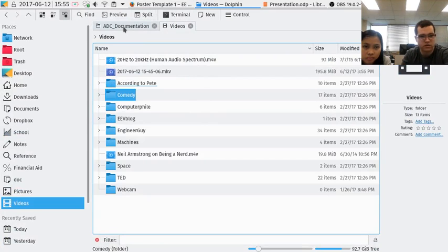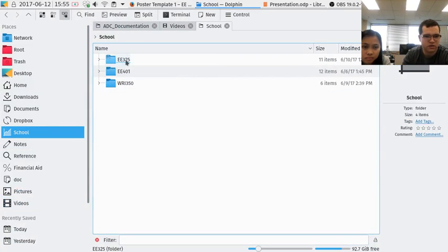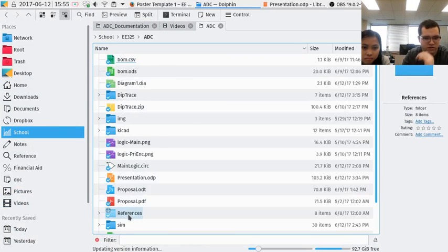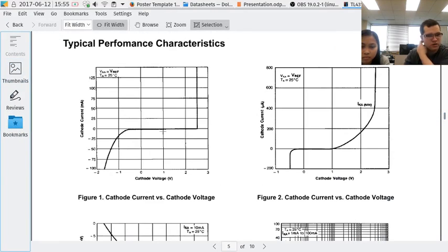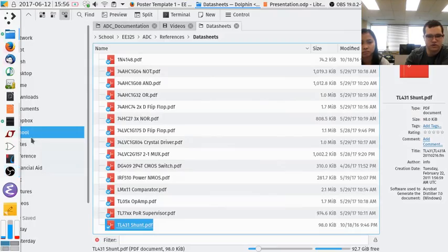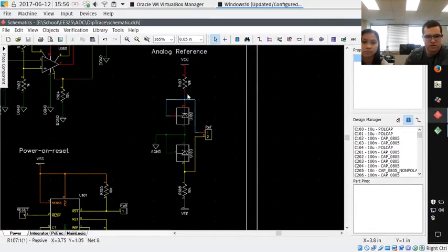So we chose the TL431. And you can actually look here. With a Zener, you'd typically have a much shallower knee here, so it would be something more like that. In this case, this thing is very sharp and handles supply rate changes very well. So basically it's a very stable Zener. Let's see here. So going back to this.